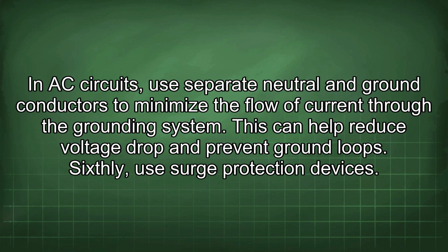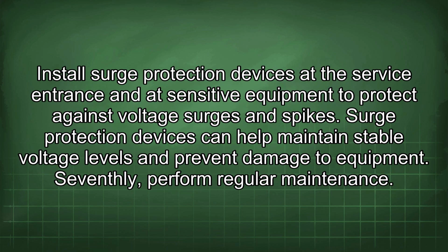Sixthly, use surge protection devices. Install surge protection devices at the service entrance and at sensitive equipment to protect against voltage surges and spikes. Surge protection devices can help maintain stable voltage levels and prevent damage to equipment.